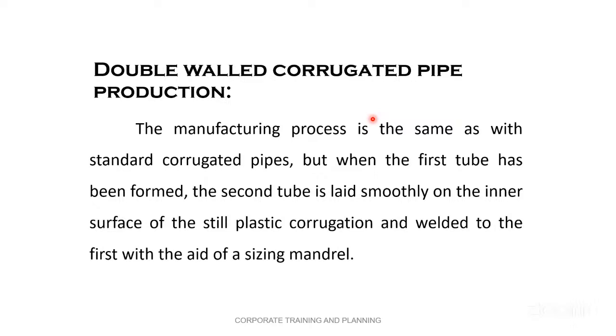And you have to keep in mind the screw output calculation, like screw rotation. The screw is designed as per the material. That is very important here. If you have a different material, you have to use a different screw. I have told you: for nylon different, for PVC different, for HDPE different. You cannot use one screw for another material.